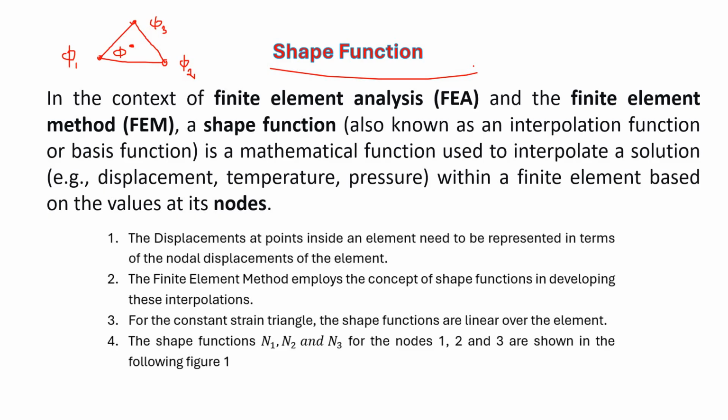Now, if you use the same shape function for all these parameters as well as for the geometry represented by Cartesian coordinates, that is, the same shape function for geometry as well as the hydraulic gradient or any field variable, that is said to be isoparametric formulation. So what is isoparametric formulation? It is nothing but the same shape function being used for defining the geometry in Cartesian coordinates as well as the field variables such as displacement, temperature, hydraulic gradient or pressure, based upon the nodal values of the element.